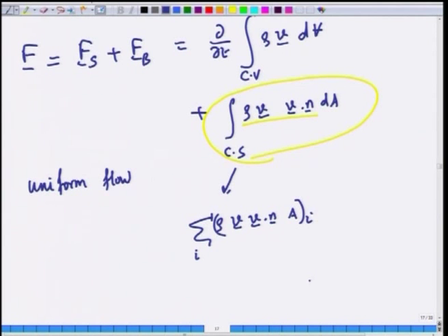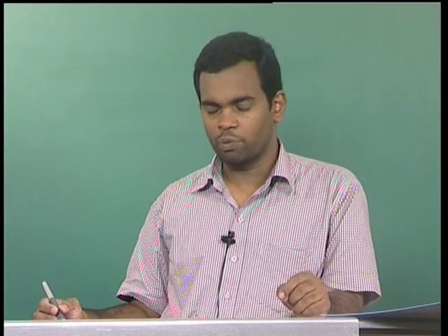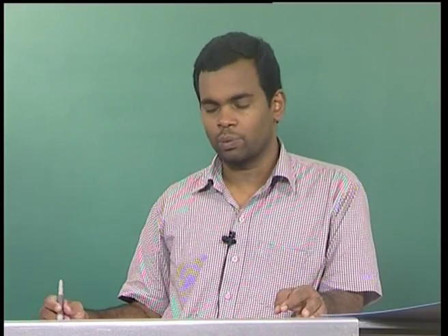Suppose the flow is not uniform. Then we came up with this momentum correction factor beta, which will enable us to write this equation in this form, but with a beta term in it, and beta is identically equal to 1 for uniform flow. But for other flows such as laminar flow in a pipe, or turbulent flow in a pipe, beta is not exactly equal to 1.